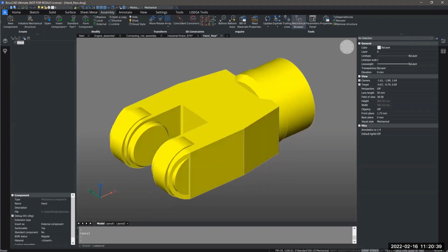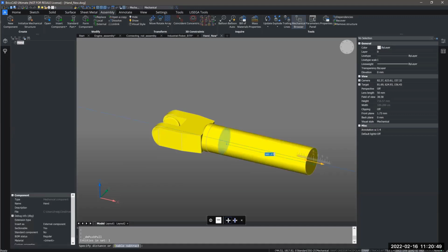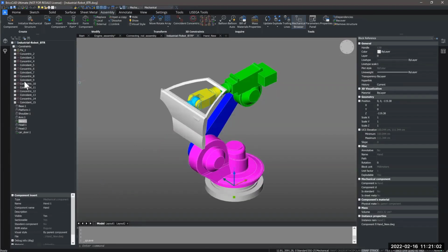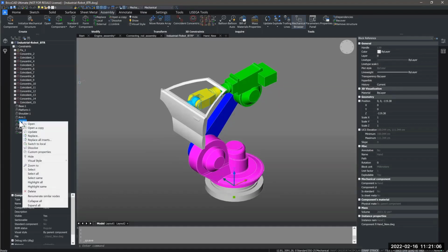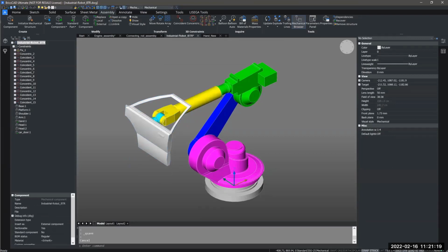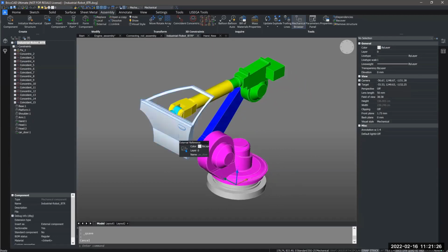From here, we can then make some changes to the file. For example, we can add some material onto the end here. You can use either the extrude or the push-pull command, I think, and we can pull this backwards 400 millimeters. Now it's made to be longer. Then we can go ahead and save it once more. Go back to the file and select the hand here. We can update this, only this part if we wish, or you can use the root node to update the entire assembly, but we just changed one part. So I will update that individually. And you can see it will extend accordingly, and it will still keep intact the constraints that we placed earlier.